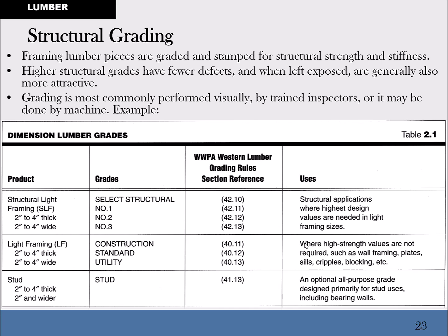But the stud means something else. It means that it has been cut after it was dry, cut precisely to a specified length. So if you have an 8-foot stud, then if it's truly an 8-foot stud, then it's 8 feet long. Exactly. And then when you go and frame it up into a wall with a bottom plate and a couple of top plates, then you end up with a wall that's taller than that.